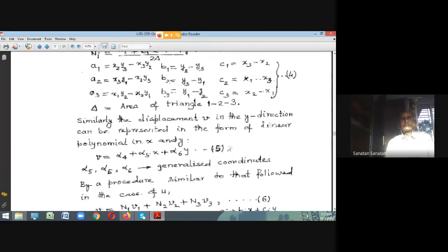It's a very important thing that your surface equation, that surface above an element, is given in terms of the three corner node displacements, and for any point the value depends on the xy value of that point. So that's how the linearization gave rise to this. And if I follow a similar principle in the case of y displacement, I can take the V surface, again doubly curved. It will have a form involving x and y.